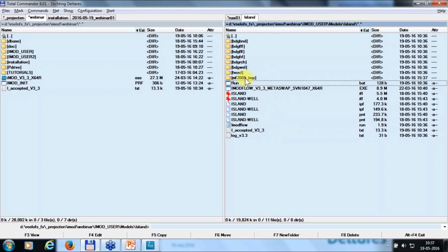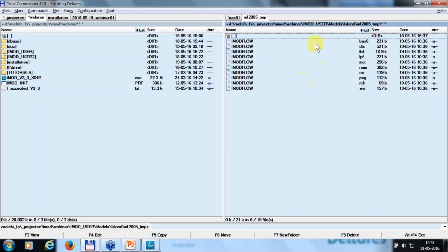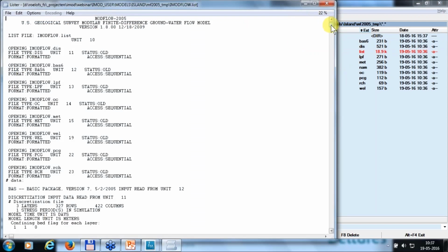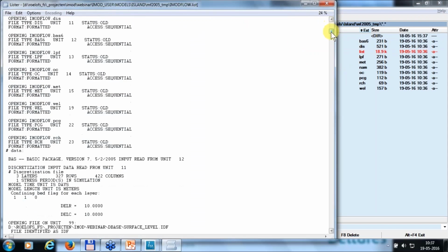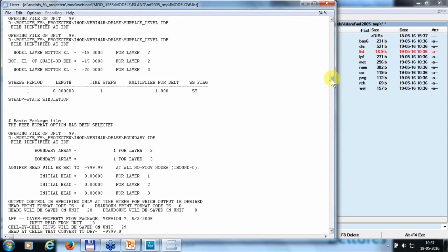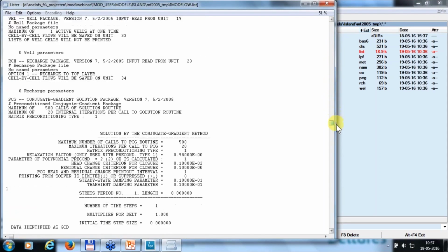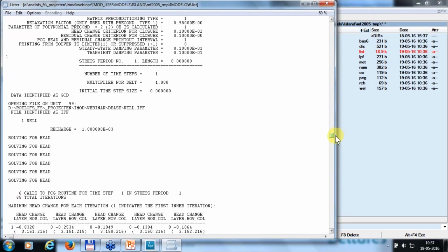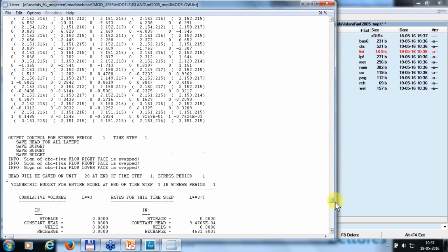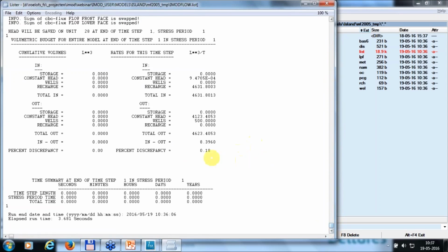Important folder is this folder, because here you can see the complete MODFLOW series of files, and if you like to see some echo of the model run, just open the list file, and this is just the standard MODFLOW echo file with information about files used, cell size, modules needed, used, and at the end, very important, the water balance of this model.